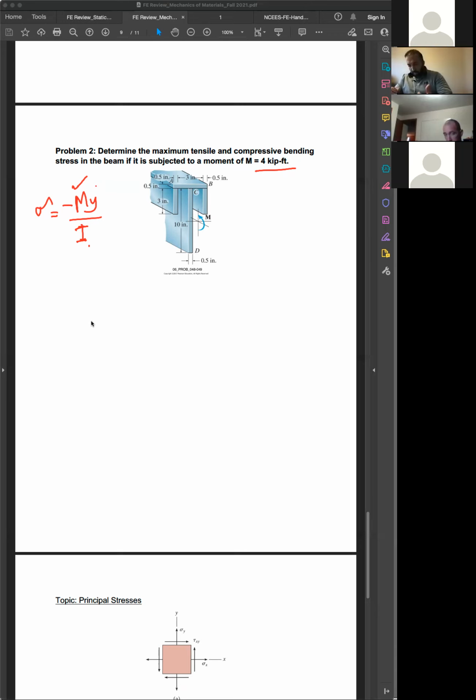The first problem you're dealing with is to find the neutral axis, because you do not know what the neutral axis is in this case, right? So we need to find the centroid and pass the neutral axis through the centroid. So let's find the centroid. y bar is equal to the summation of y tilde i times A i over the summation of A i. If I put my datum here for now and find the y from here, the way I can deal with this problem is, just the way it is shown, 1 vertical member, 1 horizontal member, and 2 vertical members.